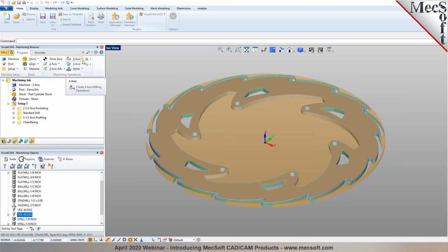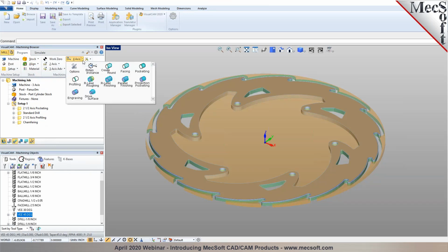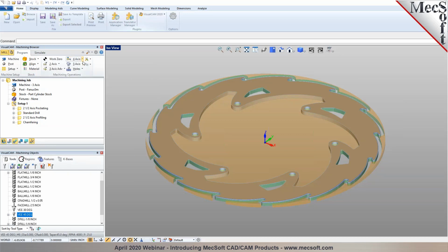We also offer multi-axis toolpath with 4 and 5-axis methods in our Expert, Pro, and Premium configurations. You can do 4-axis, both indexed as well as continuous 4-axis methods, and simultaneous 5-axis toolpath method offered in our premium configuration. Hole machining is offered in all of our configurations. We have drill, tap, bore, reverse bore, and 4-axis drilling methods are also offered.